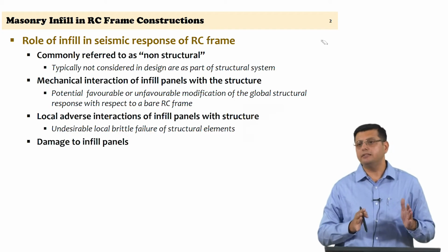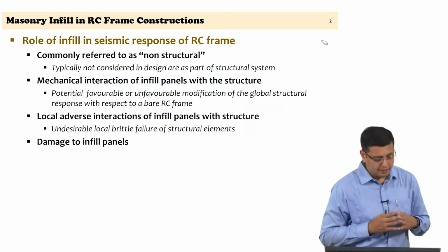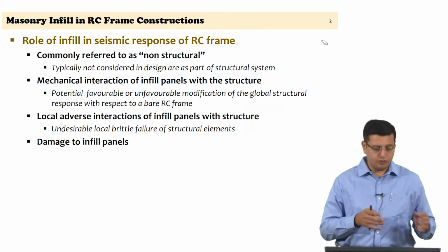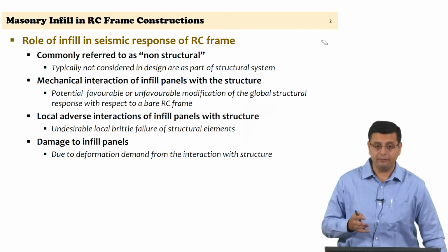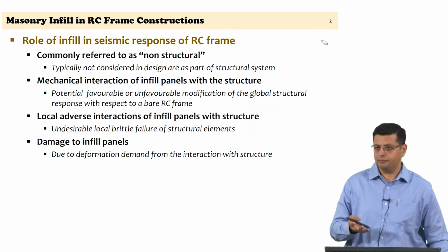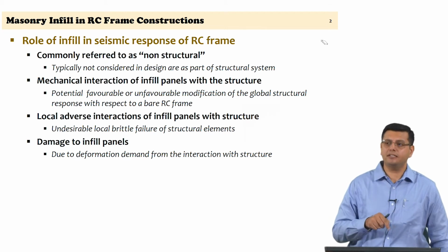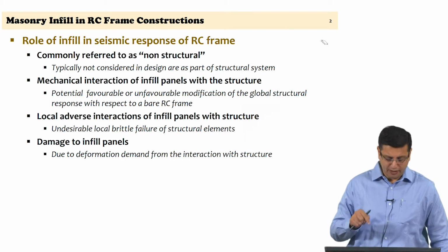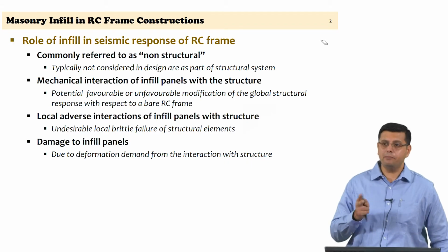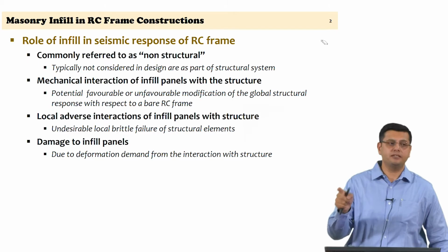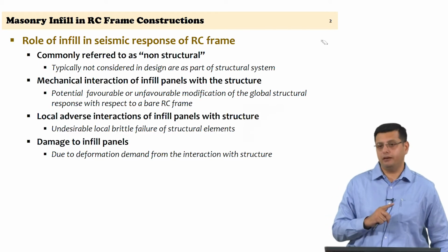So, infill panels can get damaged. The mechanism of damage of the infill panel needs to be understood, and this damage is occurring because of the interaction of the frame with the infill panel, and particularly because the deformations in the infill panel and the deformations in the frame are not similar.